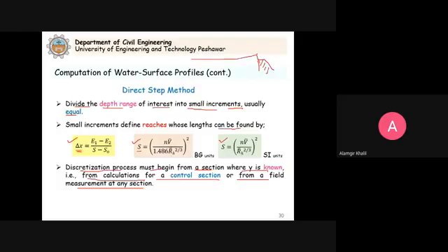This water will flow over this weir control section. So we already know the depth at the control section, and then you proceed downstream. What is the depth here? Essentially, let's say for example we have 4 feet, and downstream the depth is, let's say, 3 feet. So what we will do is that this profile will form.